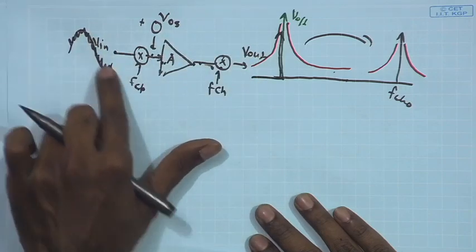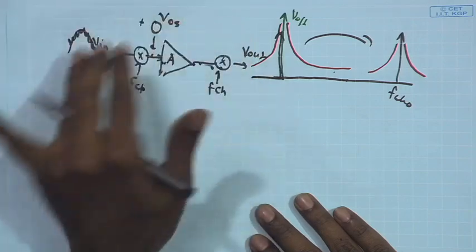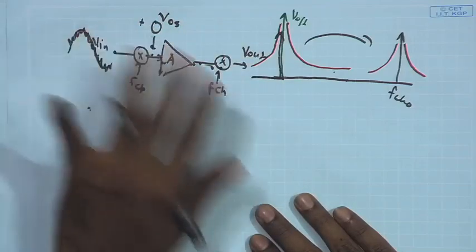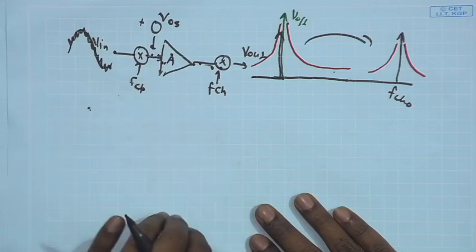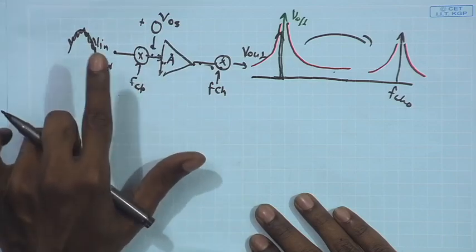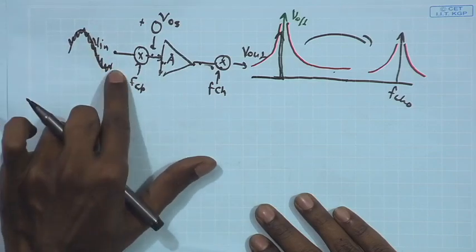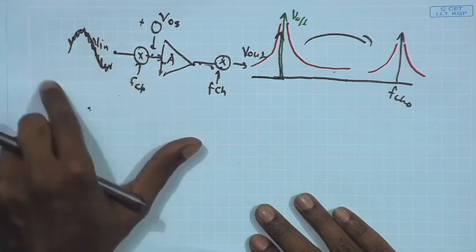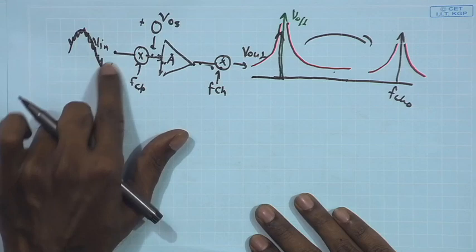So, for this particular dynamic offset, the gain can be set to 1 if I have a strong enough feedback, beta equal to 1, in the negative loop. But in that feedback loop I would set the cutoff frequency so low that the actual signal is not able to pass, only the slowly varying, undesired large amplitude dynamic offset is able to pass.